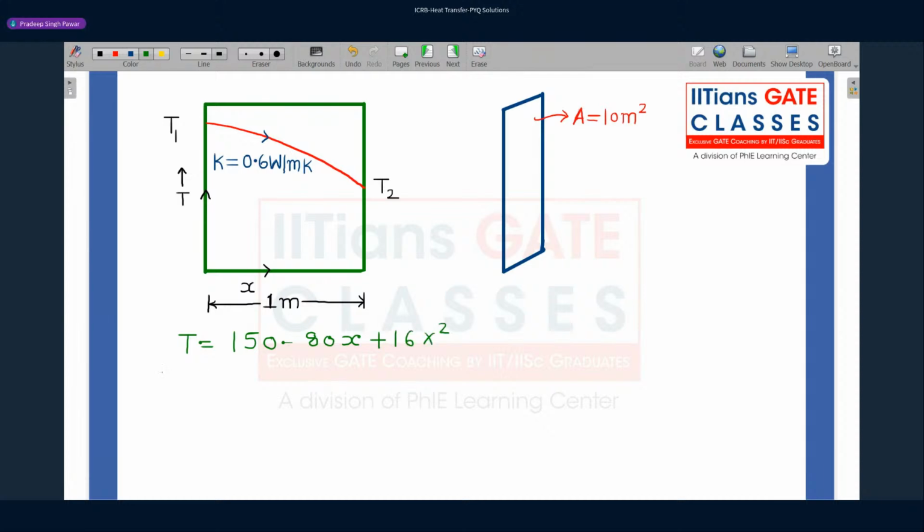If you substitute x equal to 0, you get 150, just numbers. And if you put x equal to 1, you will get a value of 86. So this end is at a higher temperature, this end is at a lower temperature, and you have a second power relation, a polynomial relation, in the temperature distribution. So temperature is continuously decreasing like this.